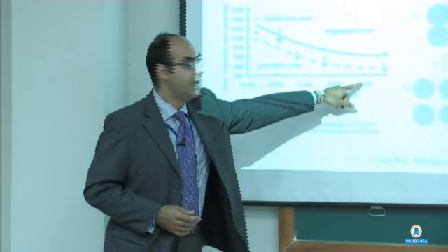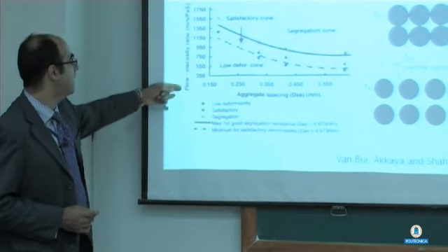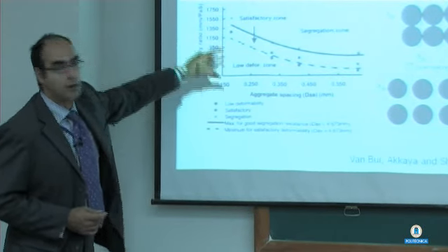the more paste you add, so the larger this aggregate spacing, the lower the value of this ratio you need, which means you need a lower flow diameter, so a higher yield stress of the paste, and a higher viscosity, because the more dilute you make your suspension, the stiffer the paste must be in order to guarantee your performance.